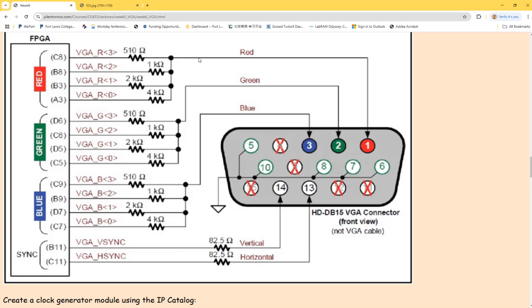So in that case, if you have V2 only, most of the voltage will be dropped where? At the 300 ohms or the 1K ohms? The 1K ohms. Is the voltage across the 1K ohm resistor VL? No. But the 300 ohm resistor will be VL because VL is over here, VL to ground.